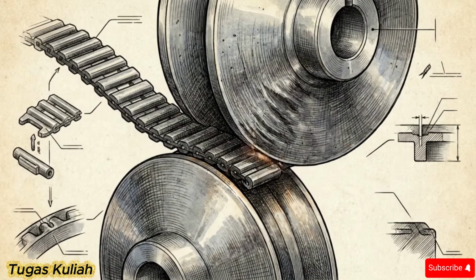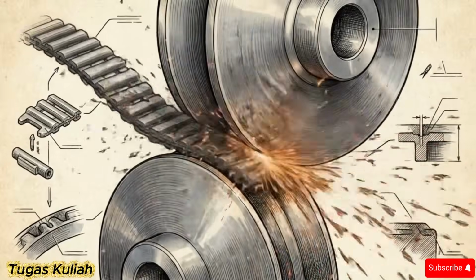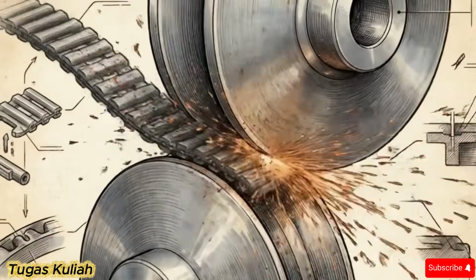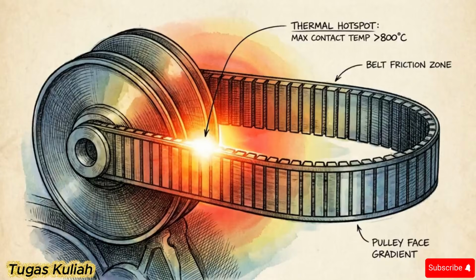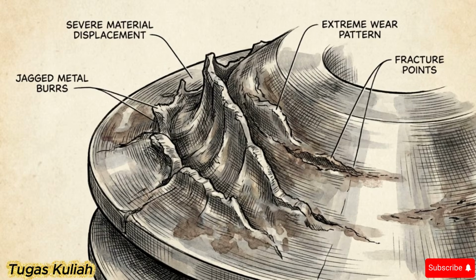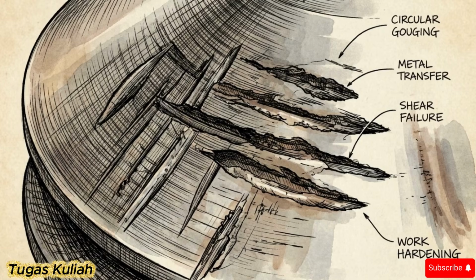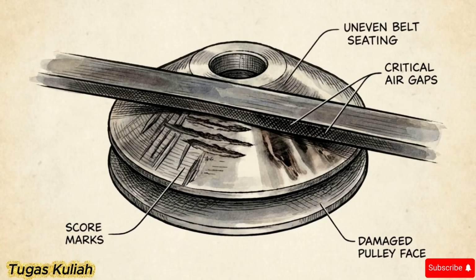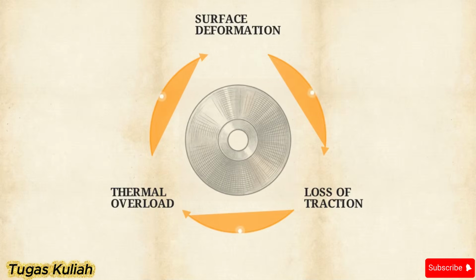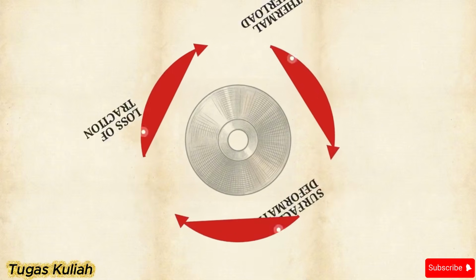Without the necessary friction, the steel push belt loses traction, violently sliding against the smooth metal face of the pulley. This metal-on-metal slippage instantly generates extreme, localized flash heating. The intense heat and sliding friction inflict permanent structural damage, carving deep scars and gouges, known as scoring, into the previously pristine metal pulley face. Once the surface is scored, the required friction coefficient can never be re-established. It triggers a runaway feedback loop. The scarring causes exponentially more slip, which generates exponentially more heat.